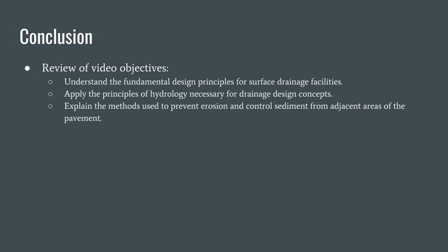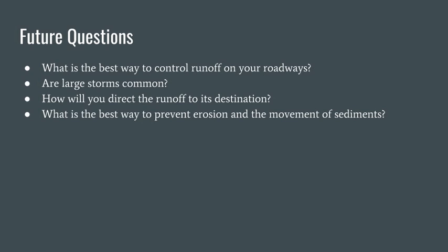This video showed that roadways are fundamentally designed with different slopes to assist with runoff. Different structures are put into place for this runoff to drain, and there are countless ways to prevent erosion and sediments from getting onto the pavement or into the water supply. So some future questions that one might ask are, what is the best way to control runoff on your roadways? Are large storms common? How will you direct runoff to its destination? And what is the best way to prevent erosion in the